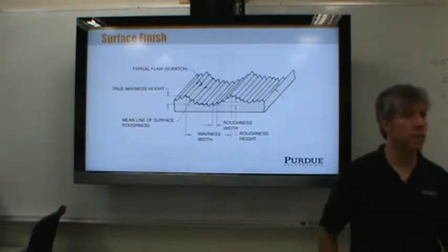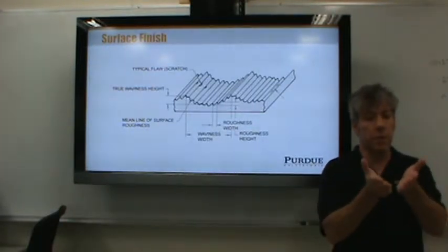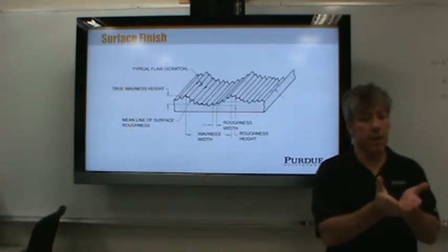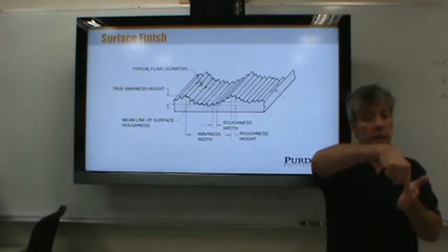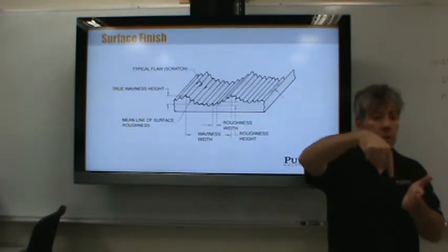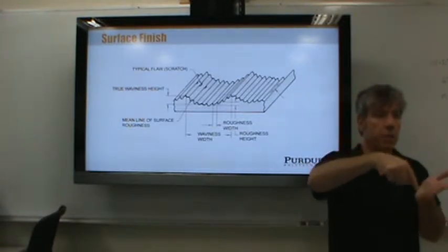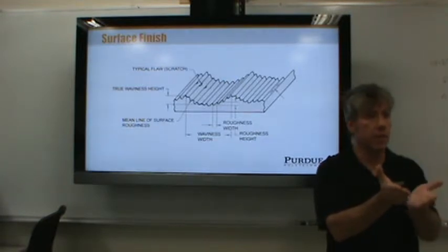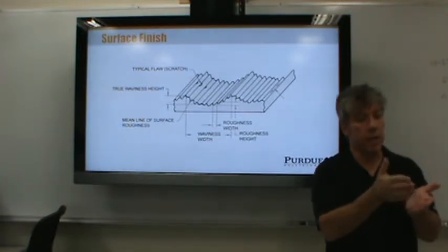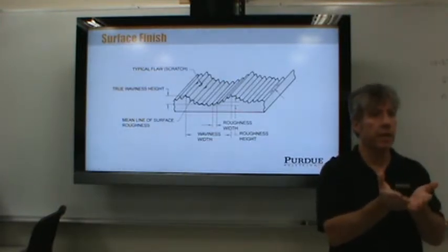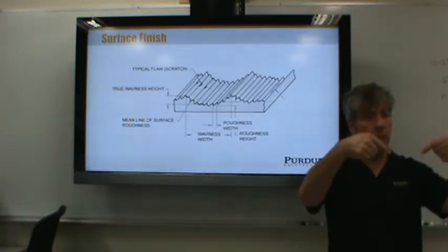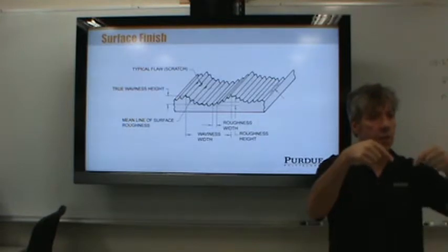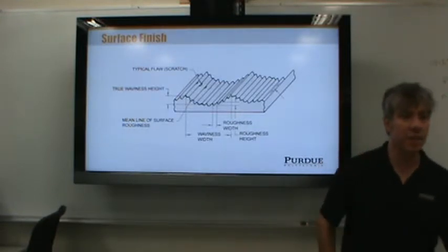It was really interesting because the grooves on either side have ridges in them, what we would call roughness really. The needle sits down and is deflected in this direction diagonally due to one side and deflected the opposite diagonal for the other channel. So your channels, left and right in stereo, are on either side of the groove. And there are detectors on the head so that as the needle deflects this way, it picks it up as the left channel, this way is the right channel. It's pretty clever, it's interesting.